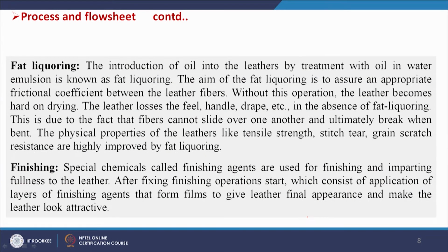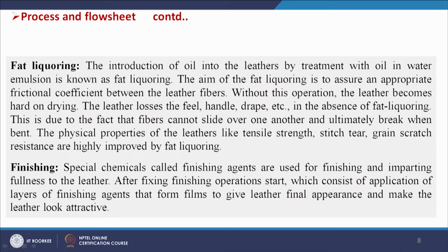Next step is fat liquoring. So, the objective is that some oil will be allowed to go through the pores of these hides, and the introduction of oil into the leather by treatment with an oil in water emulsion is known as fat liquoring. The aim of fat liquoring is to assure an appropriate frictional coefficient between the leather fibers.